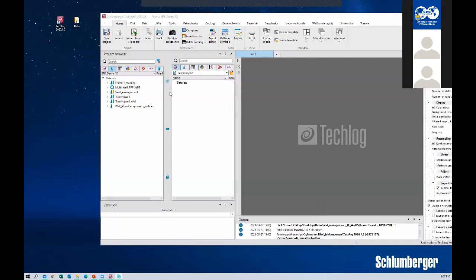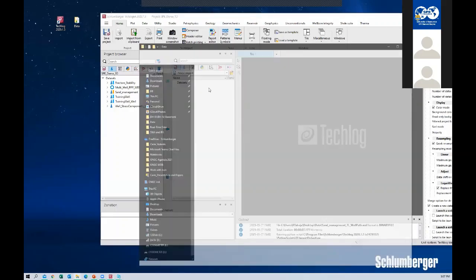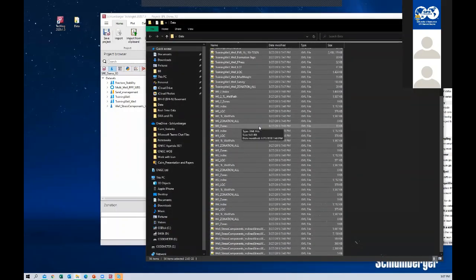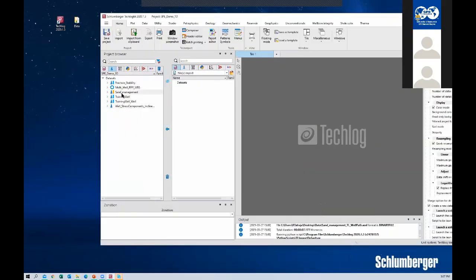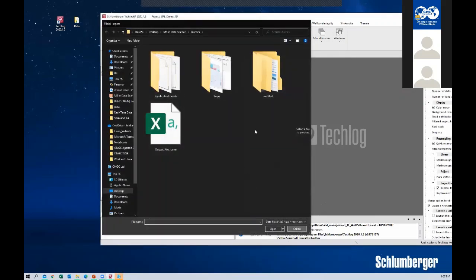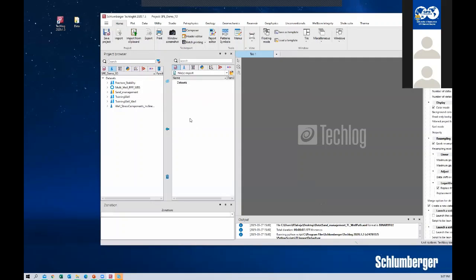Okay. Sorry for the break. All right. So hope you understood how you load the data. There are two ways mainly. If you want to do it conventionally, you can go to home and click on import. This section will open up. You need to choose the type of file you want to load, such as an ASCII file or an XML file, and then choose the location where the file exists using this particular folder. The file will open up over here, and then you can import.